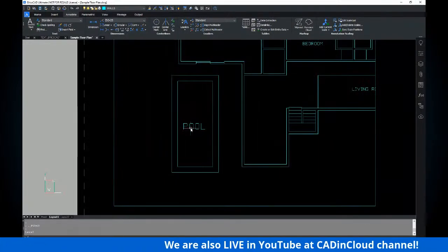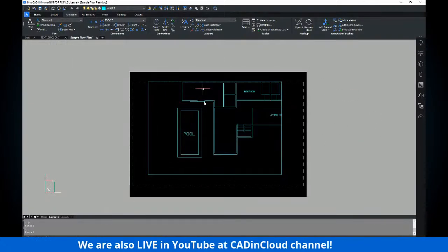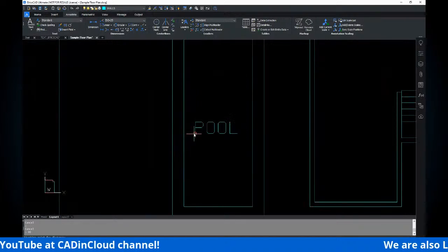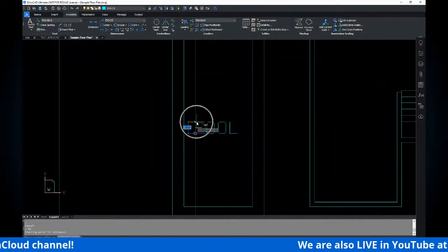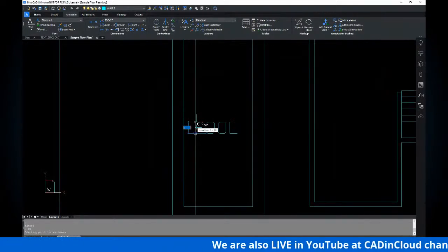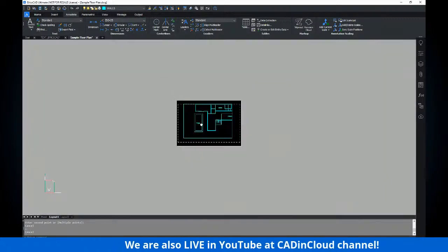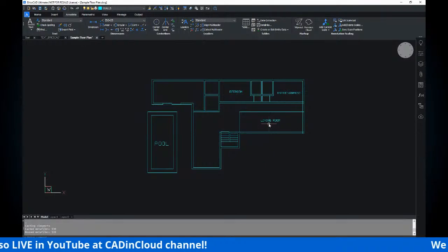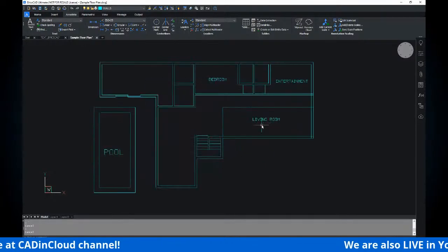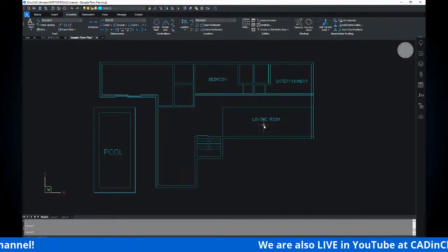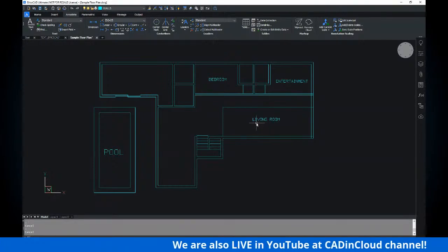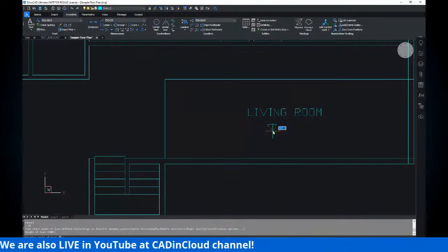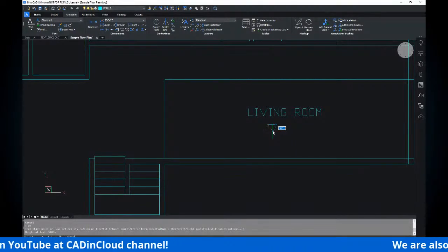If we measure that outside of your paper space or layout space, it will be exactly 5 millimeter. That will be its measurement. Because, guys, if you put the actual printing height of the text here on the model space, I'll put 5 millimeter. Let's say living room.